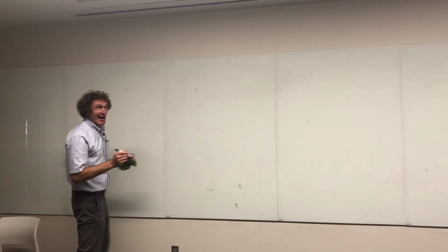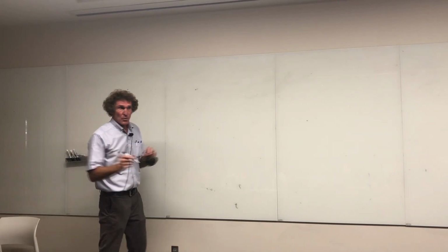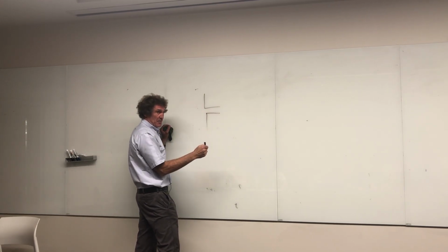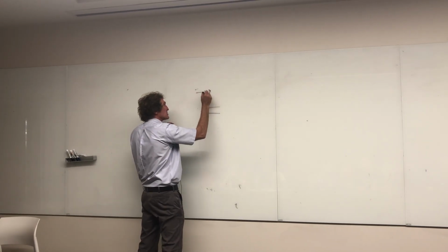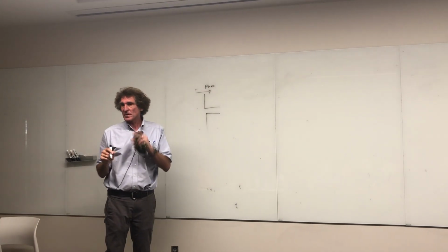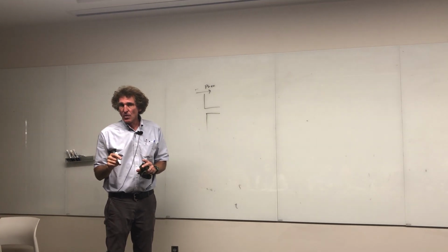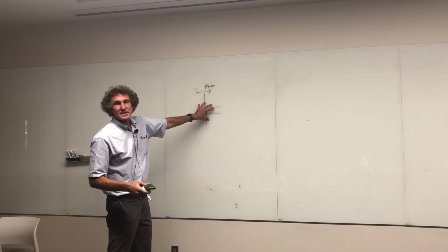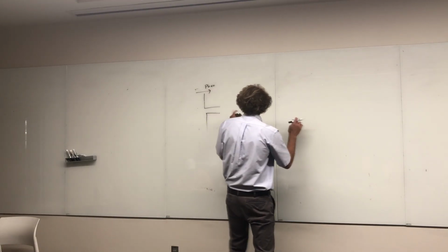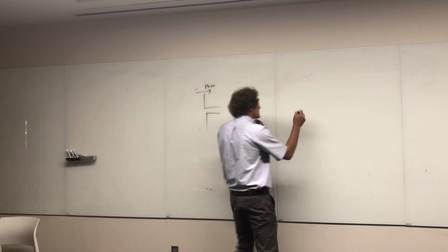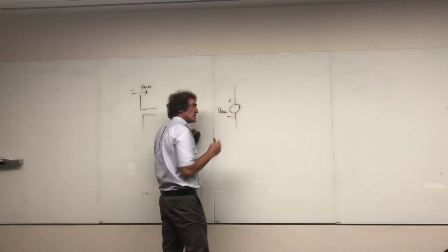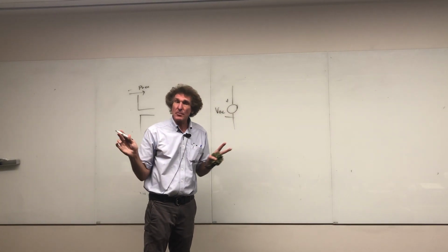All right, so now we're going to do this. We're going to assume I have an antenna here, and I've figured out through the Friis equation how much power is received. So I know what the power received is. So what does that power received really mean? Well, I know the antenna itself has an antenna impedance. So here's what happens. We take this antenna system, and we say it is equivalent to some voltage that we term V open circuit. That's on the antenna, the open circuit voltage that we don't know yet.